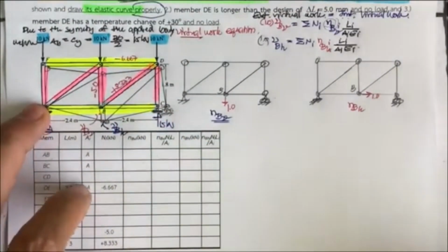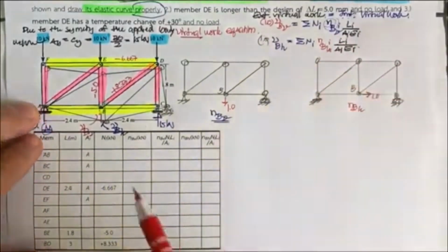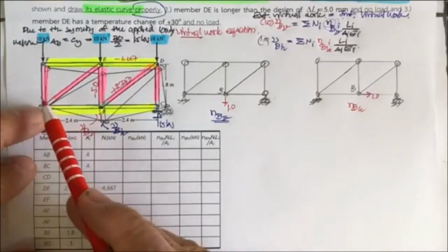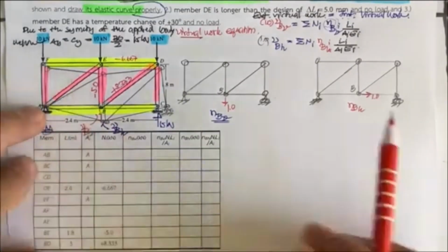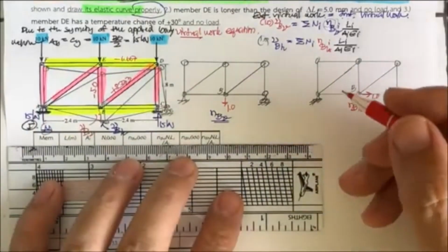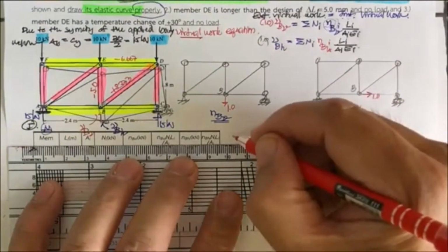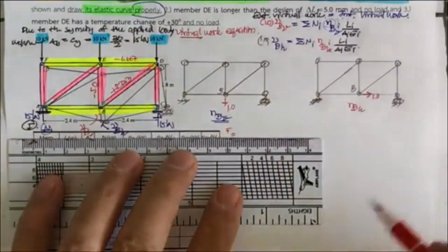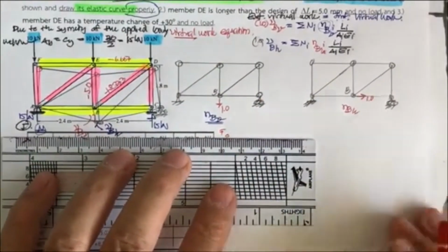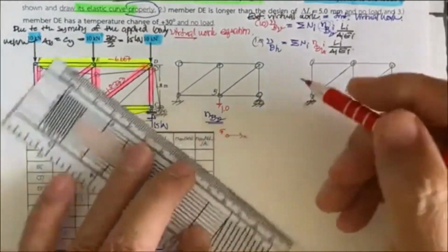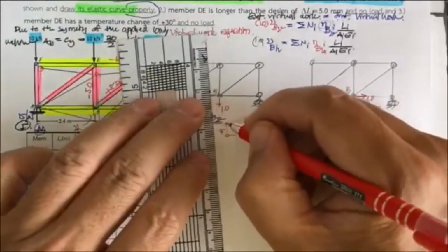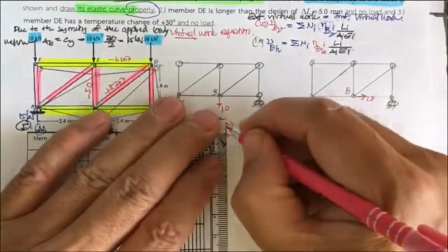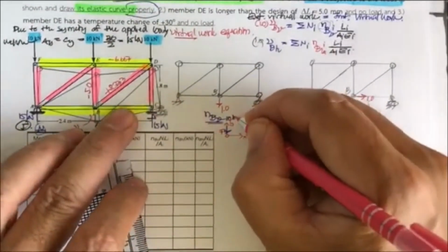Now we're going to determine the rest of it. By starting the determination of the members, can you start with A? No, A has 1, 2, 3 unknowns. You may start with F because F has 2 unknowns. By doing that, just take a look at the method of joints. This one is going to be F. We put this in the X direction and this one in the Y direction, and it's subject to 10 kilonewton. So the force here is 10 kilonewton.